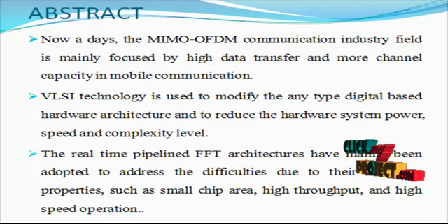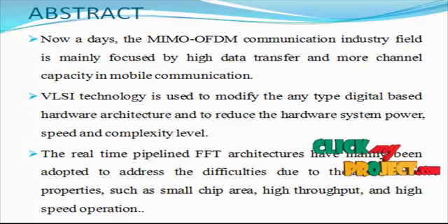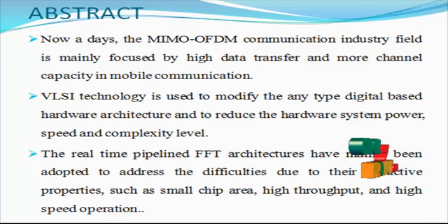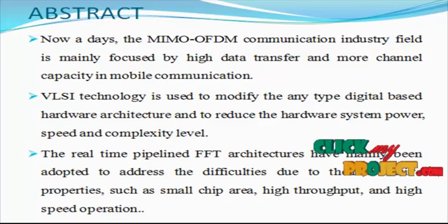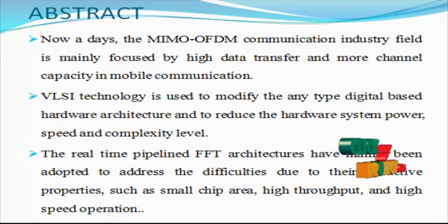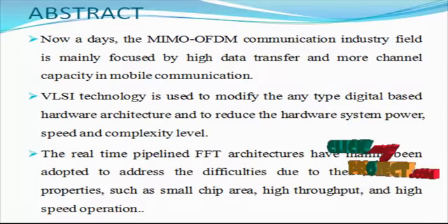Hence, it is possible to reduce the arithmetic resources of the conventional complex multiplier by a factor of 2, leading to 100% utilization. It is ideal for two consecutive complex input data to contain the complex number on which to execute the complex multiplication. If so, we can minimize the reordering memory requirement while achieving the above objective of reducing the arithmetic resources for the overall multiplying process.